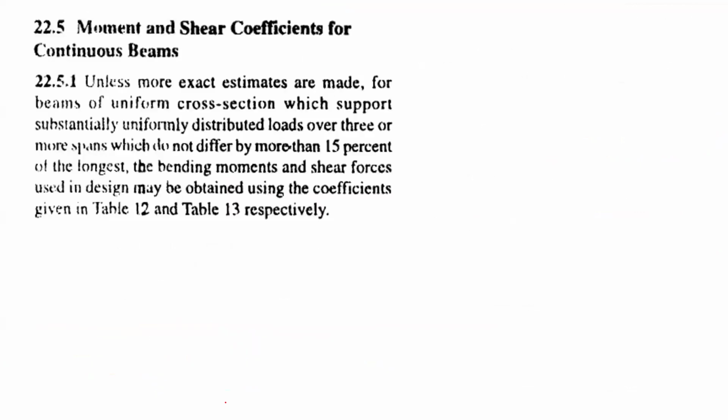Then moment and shear coefficients for continuous beam. Now most important in this is when we can apply this. These two conditions are the most important ones. First, a minimum of 3 spans are required. Keep in mind, this is the most important one.